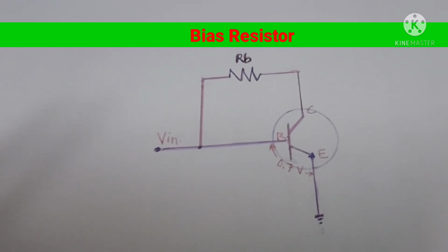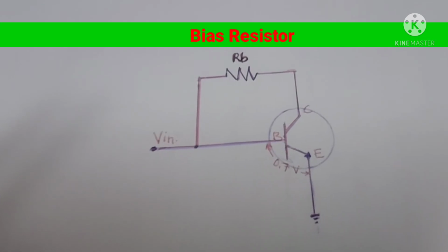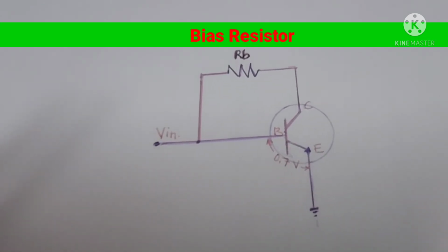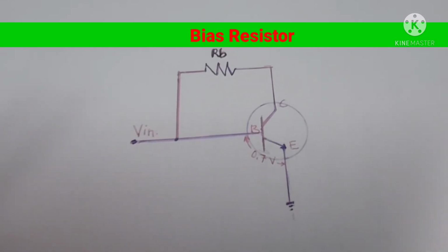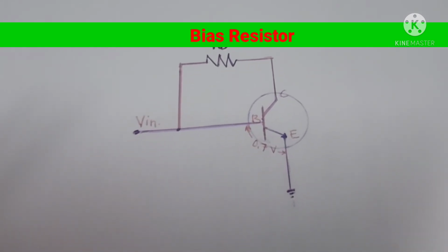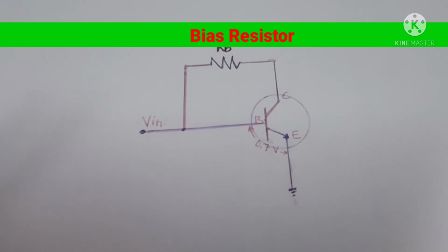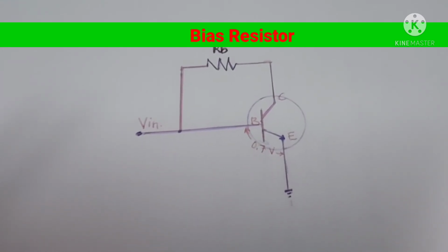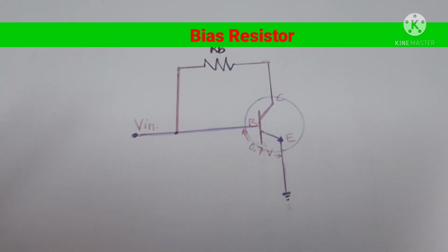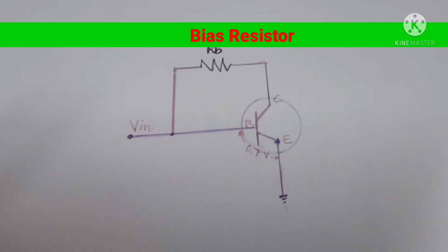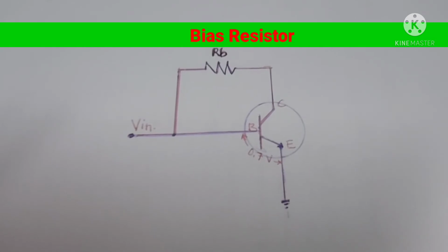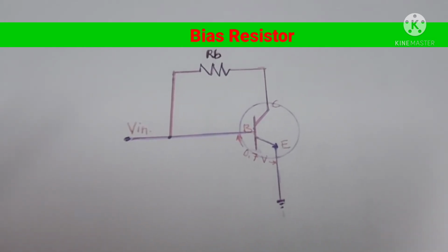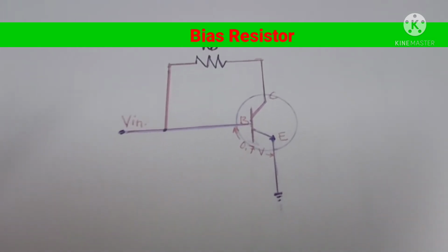Transistor biasing is the process of setting a transistor's DC operating voltage or current conditions to the correct level so that any AC input signal can be amplified correctly by the transistor. This is the self-biasing resistor or the feedback configuration.